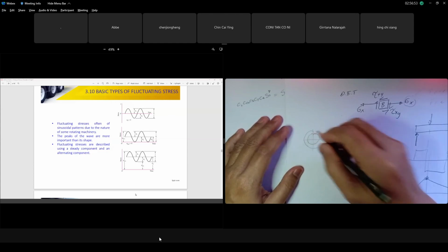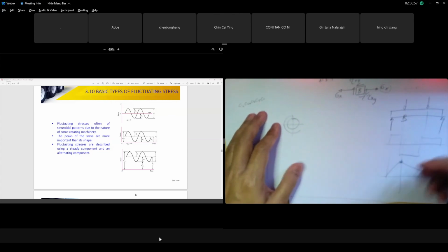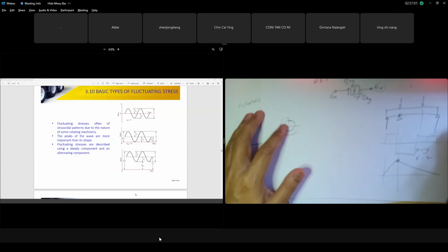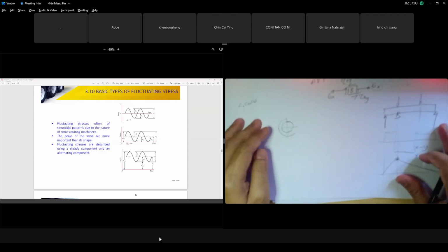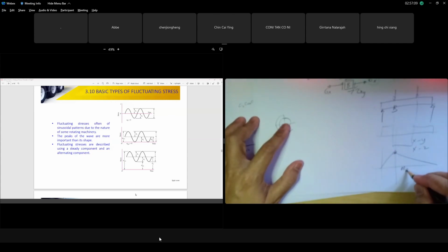It means for your element at point B, you plot your bending stress. Previously, in your shaft analysis, you combine both the XY plane and the XZ plane. The total moment at B is the square root of the moment in the XY plane squared plus the moment in the XZ plane squared.